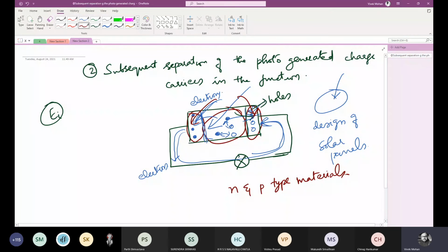So a solar cell has to be designed such that the electrons and holes can reach the membranes before they recombine. Once electrons or holes are formed, if we wait for some time, they will recombine. Before that, we segregate them through these two membranes, and we allow the charges to flow through the circuit and recombine, so that we get the potential difference across the load. So the time it requires the charge carriers to reach the membranes must be shorter than their lifetime. It should be done in a very fast manner.